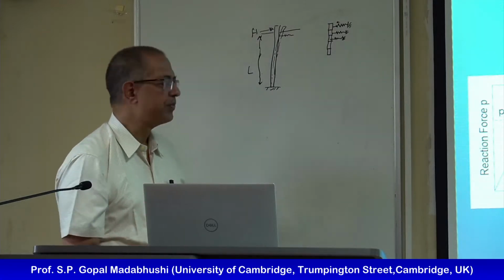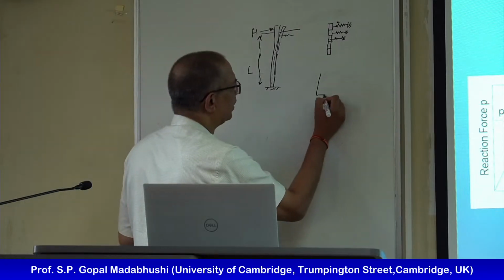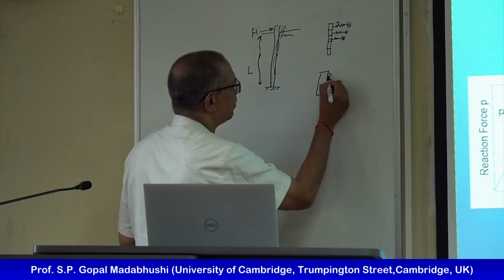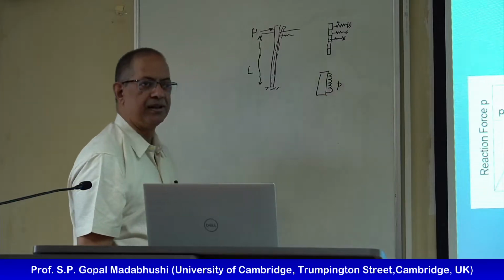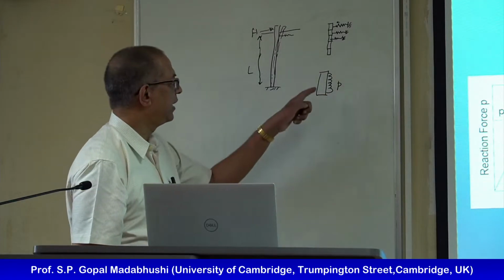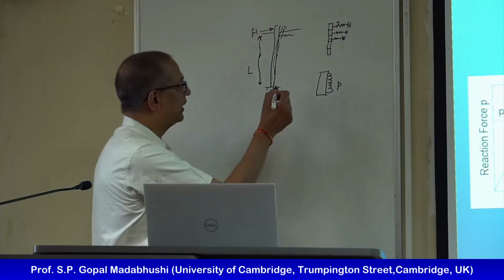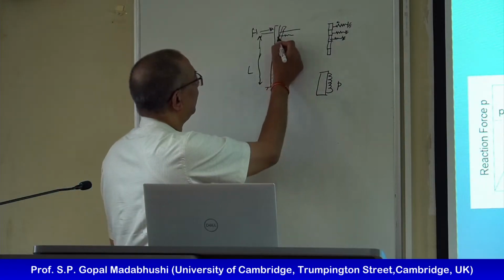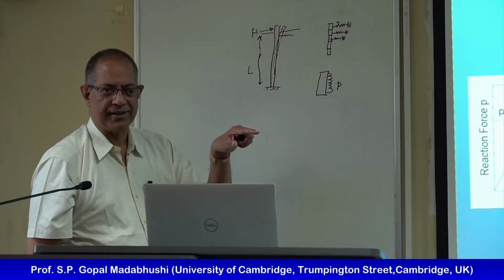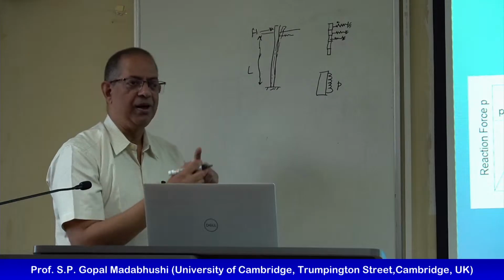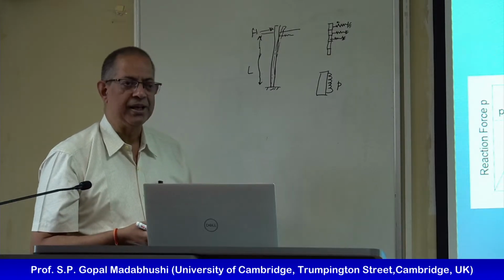So each element will have some amount of pressure P, and that depends on the deflection. If it is in air, we can work out how much the deflection is. If it is in the soil, we expect the deflection to be smaller.